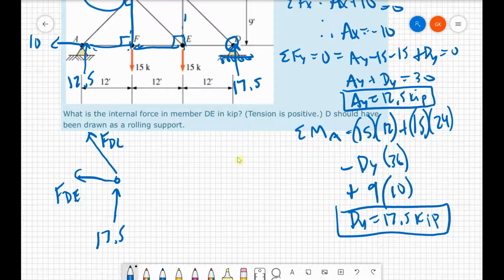So the first one I'll do is the sum of the forces in the Y. I'm doing this because I'm your omniscient teacher and I know what to do in here. And this guy right here has a slope triangle of 4 on the bottom, 3 on the side, and 5 here. We're using that for my components.